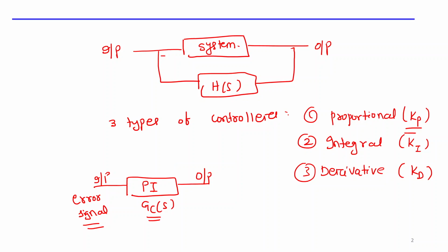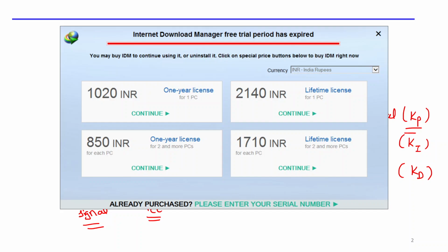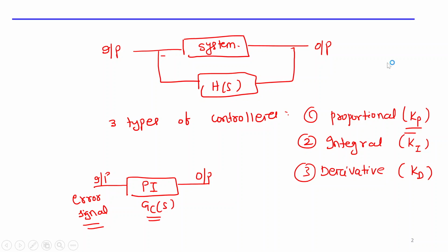Generally, when you are going to design a control system, the main focus is that you have to design the system dynamics. What do we mean by system dynamics? You have to model the plant according to the input, output, disturbance and noise. Then, after doing some small signal modeling or large signal modeling, whichever is required for your system, you come up with a compensator that can minimize the error, so we can properly track our output to whatever reference we give.